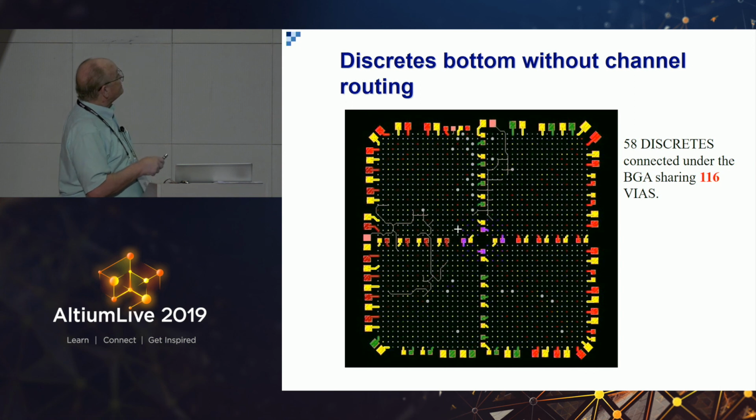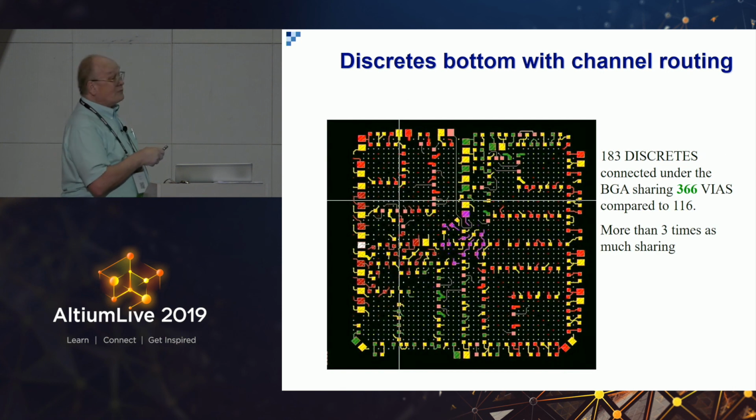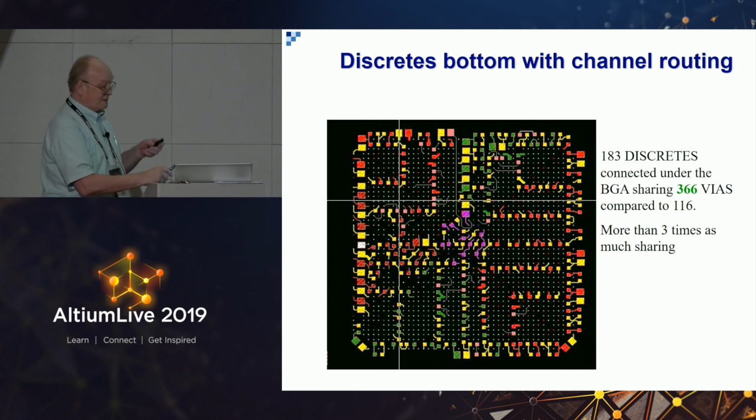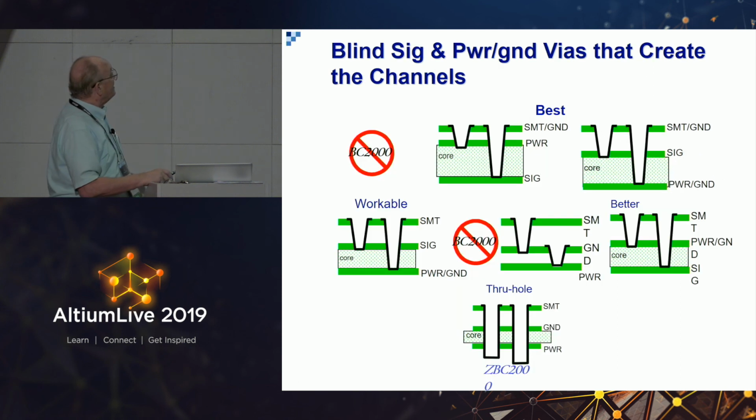Then on the opposite side, when you have through holes, there's just a forest of holes, so your components have to go outside. But once you use the blind vias, you can now put components inside the footprint of the BGA, which many people do. They put their pull-up and pull-down resistors, decoupling capacitors right inside the footprint. It's not outside. It's on the opposite side of the board, taking advantage of the space they've saved.